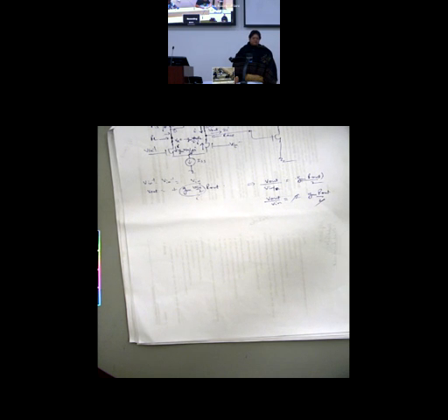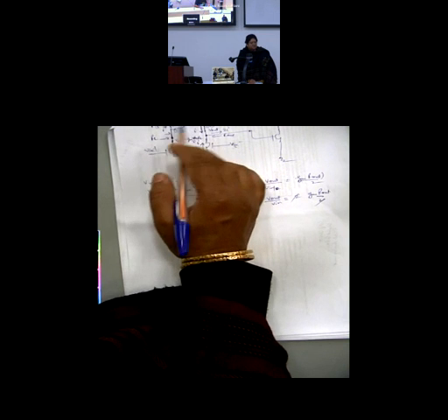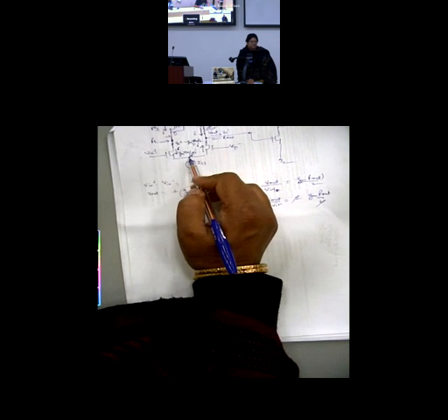Now suppose I work with the same concept. Let me apply my input differentially, so that the first cause I am removing, the first source of AC voltage. So let me apply V in plus and V in minus, so that this will give me AC ground here. This is not causing any AC voltage to appear over here, but unsymmetry will cause an AC voltage to appear here. So let me see under what conditions I will still get a difference operation.